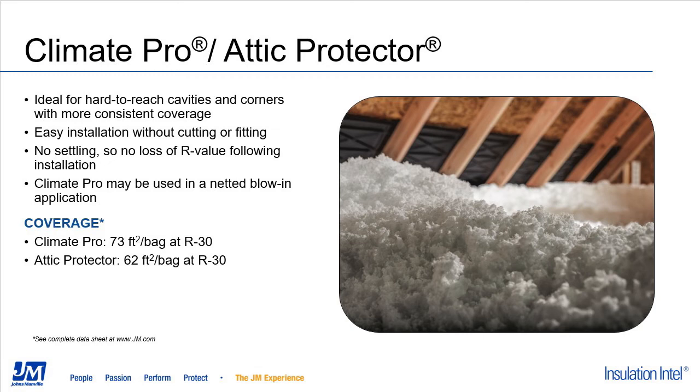It's typically used to insulate an attic space. It's typically more efficient to use blowing wool than a bat or a roll product. So you have an operator in the attic holding the end of the hose, the other at the machine loading the material. And that's typically, like I said, in an attic, but it can also be used in a wall cavity in a net and blow application where you put up a netting. You can blow into a vertical wall as well.